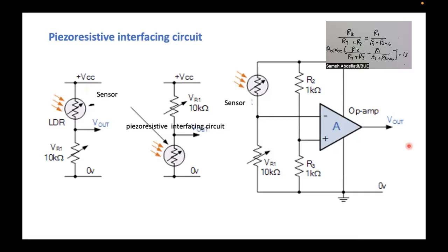But just to examine the trade-off, the circuits on the left-hand side are very straightforward, very simple, but they have a problem with the loading effect. We complicated the circuit a bit to make it isolated, to make it differential, to control the voltage range, all of which is of course great. However, you have to consider that we pay in complexity, because if you remember, I showed you in the first lecture the internal schematic of this differential amplifier. It has a very big number of transistors connected together in multi-stage amplifiers. This is not just a triangle. It's more than that. A lot of transistors are inside.